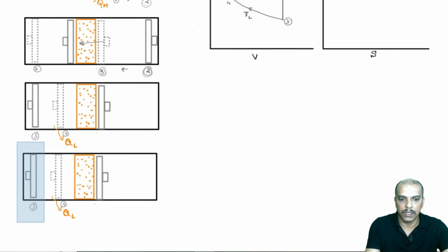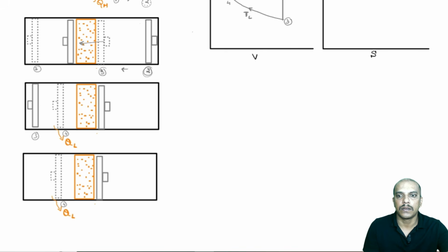Now, this is no longer there, we are at this position 4, this is what is the actual position of the piston, okay. Now, we should move at constant volume, and that we have discussed. So, that means this volume should remain constant, the distance between two pistons should remain constant, and we should move towards right.